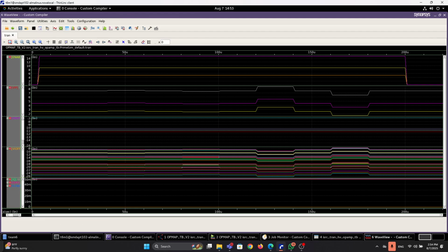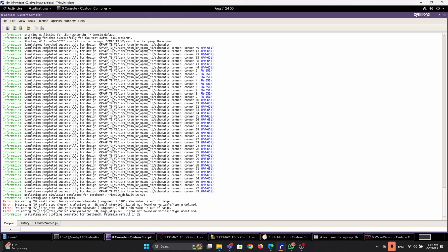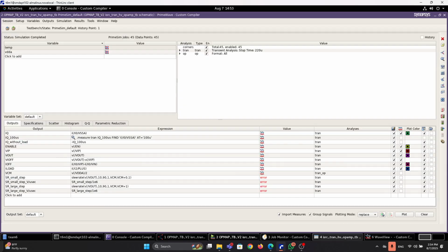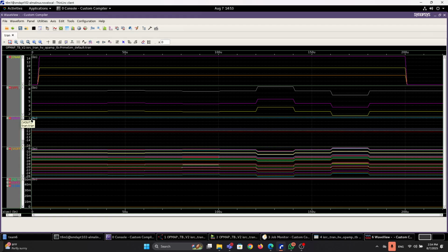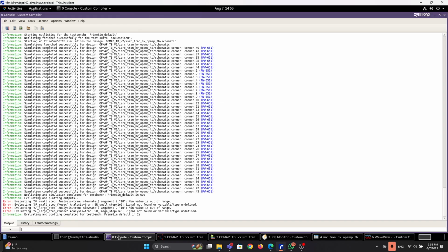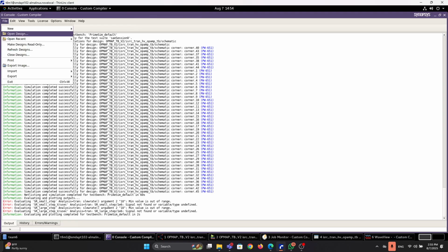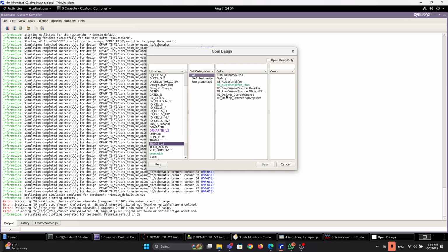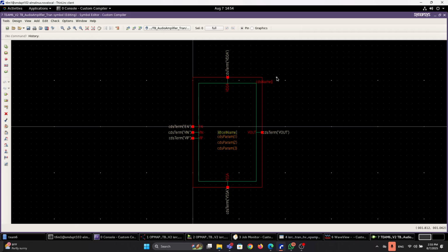Yeah, I think you need to check the functionality, because you can see the Vout is a negative value. Can I see your schematic as well? Because maybe your PMOS, you also put it to the VDD, and see if it changes. Yeah, Stephen, do the same as what Mohanad did just now. Open the schematic and then look at the corner 21, see whether the DC operating points of all the MOSFETs are correct or not.